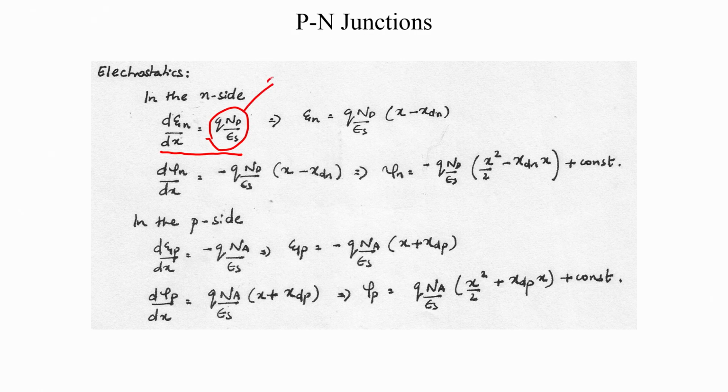because this is a constant. It's a constant because we have not considered the free carriers, n and p, and therefore the electric field is simply given by this term here. And you will already recognize that a boundary condition has been applied. What was the boundary condition? If you only look at the n side, we can draw the band bending diagram as this.